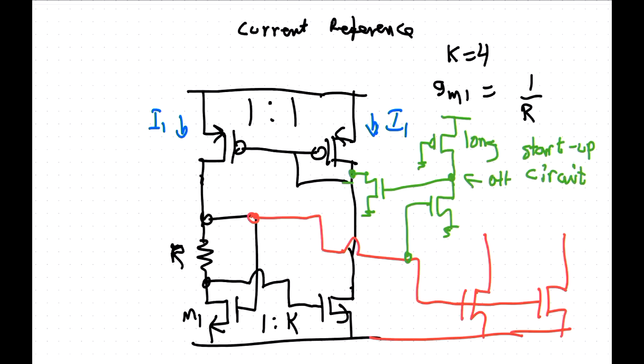Basically, can we just boost the current at the output side, with a current multiplier? I don't know if I would put in a current multiplier. If you need to drive a large amount of current at the output, I would probably put in a voltage buffer. Yeah, we could solve that issue maybe with this simple thing.